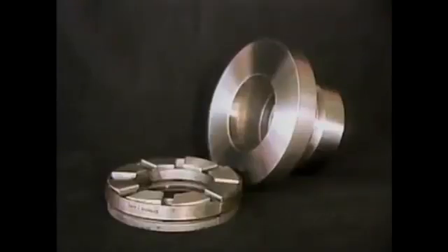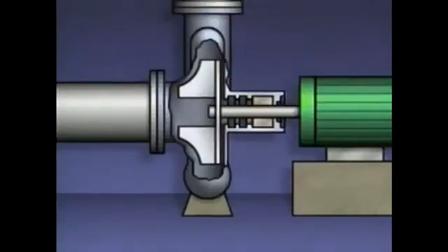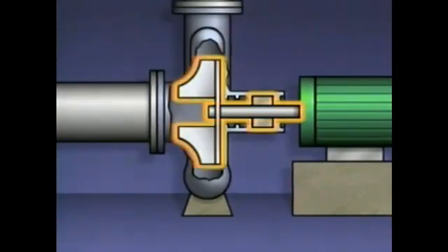Thrust bearings prevent axial movement, which is along the axis of the shaft. By allowing the shaft to rotate while keeping it in position inside the compressor, the bearings keep the impellers or blades from hitting the stationary parts and being damaged.